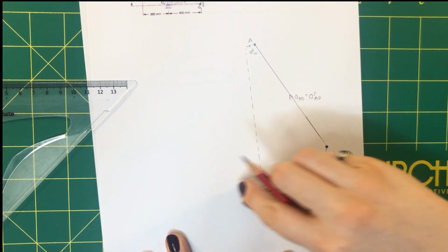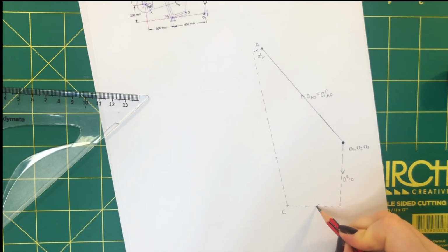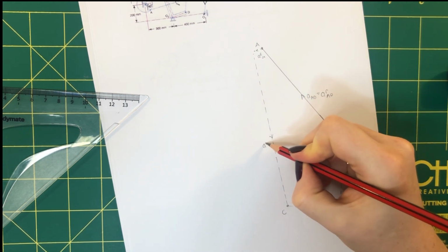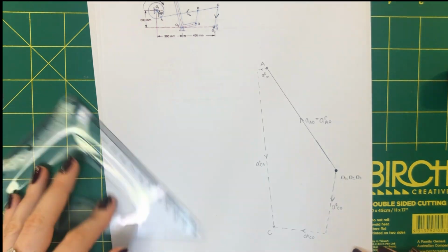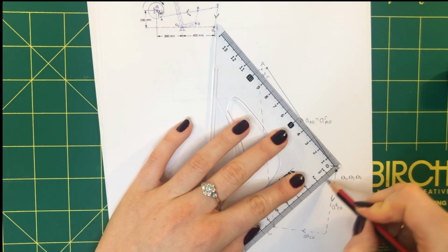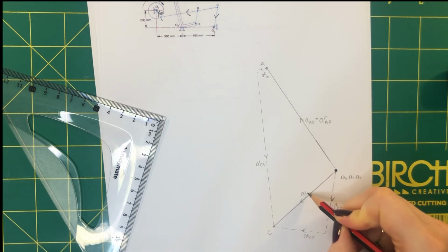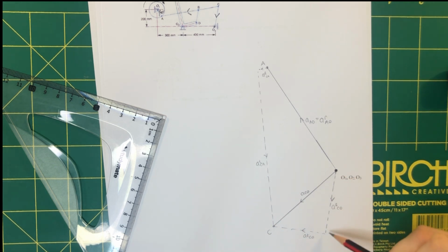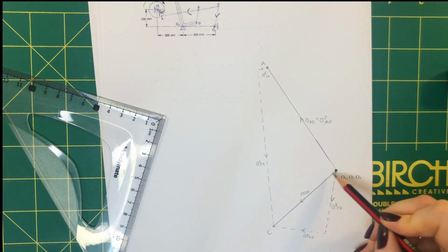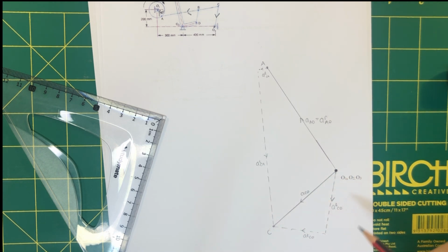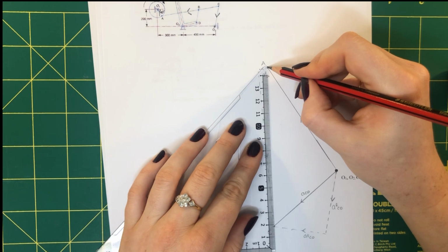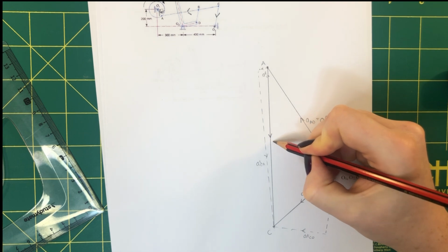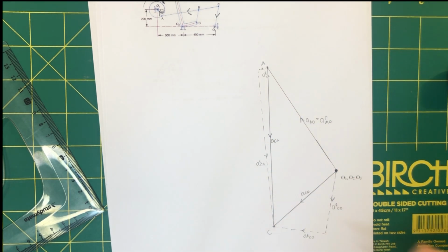So before I move on, I'll clean up my diagram. I'm going to label this tangential CA, and I need to draw in the total acceleration. So this would be acceleration of CO. I can get from my fixed point to C by adding the radial plus tangential, or I can follow the direction of the total acceleration. And we'll do the same with C relative to A. So radial, tangential, close the triangle with my total acceleration.